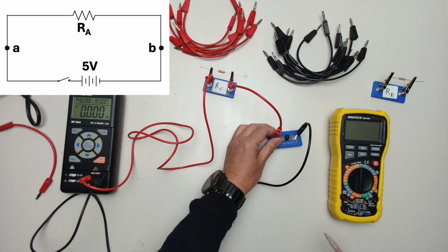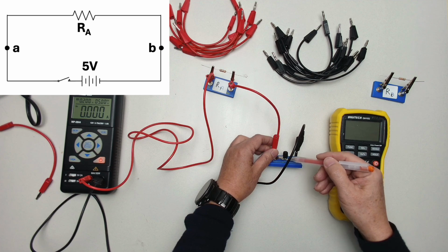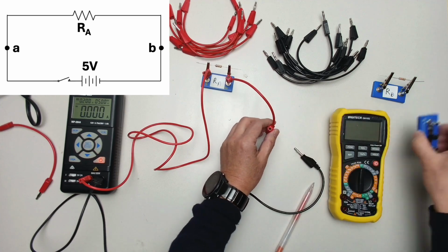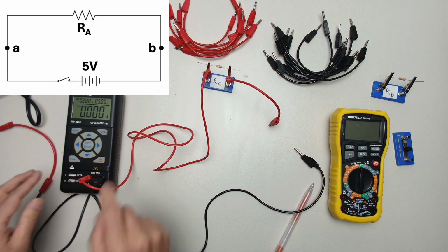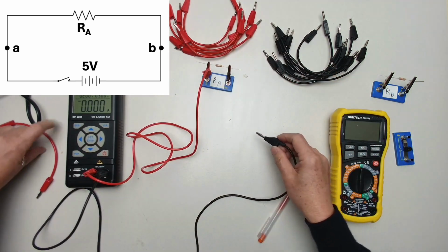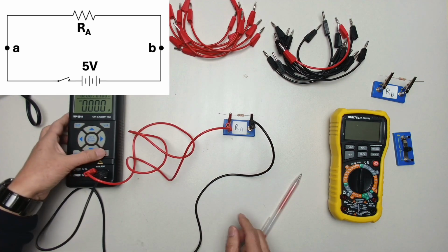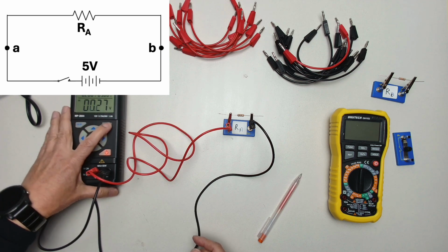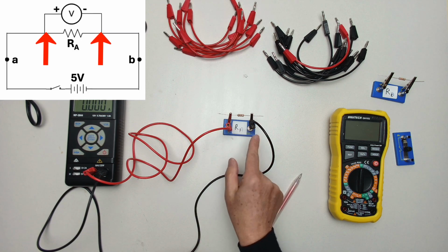Now sometimes I find when we later measure the voltage or current, the contact will affect the value. So in this laboratory, I tend to remove the physical switch, and we use the switch from the power source as our switch. So I can reconnect this one here. And you can see here, if I turn this one on, it will give you 0.027 amp, and 4.99 volts.